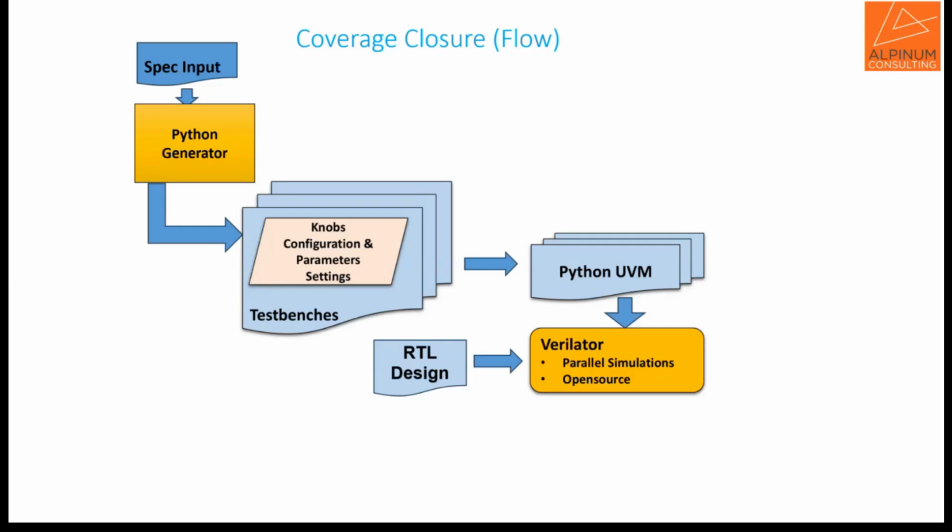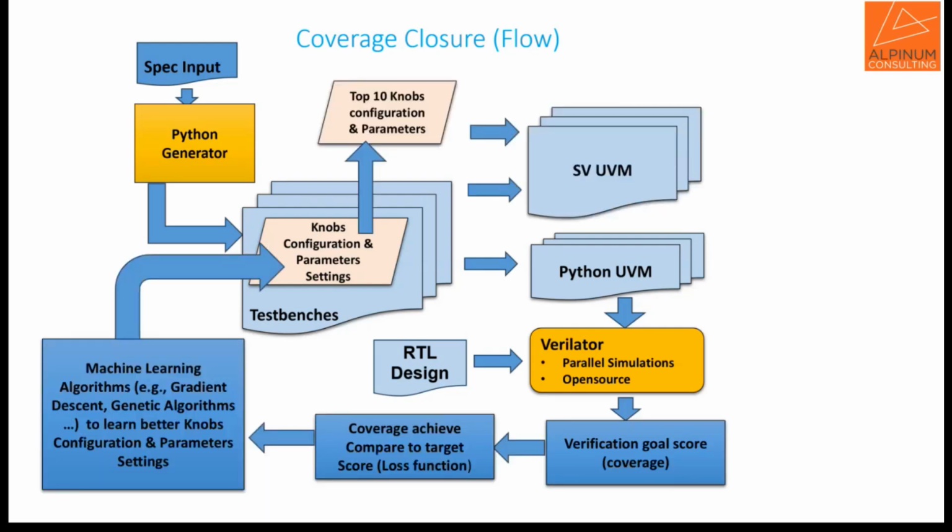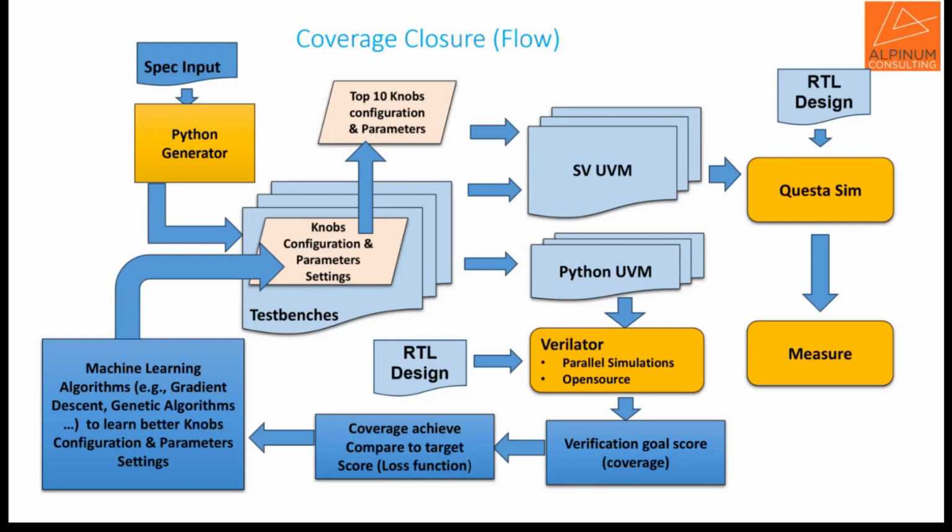So if we go to the complete flow diagram now, it will show you how we are gauging and measuring the verification goals in terms of coverage, and optimizing it with our feedback on the next iterations and runs, so that it gives the optimized result for the next time and the most targeted results, running only those simulations which add the most coverage.